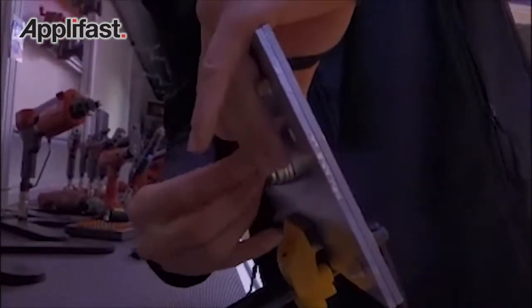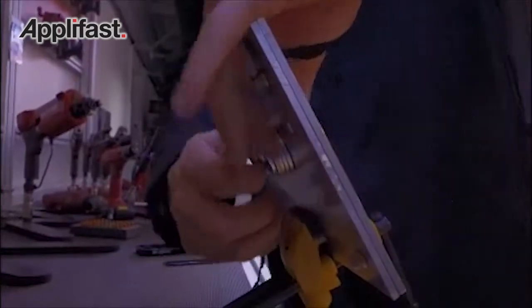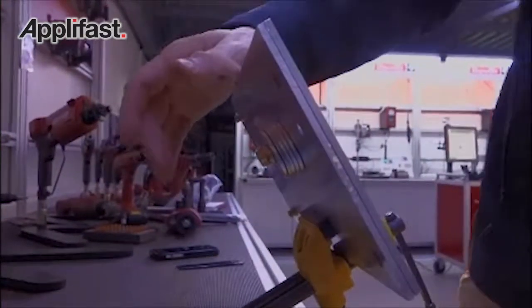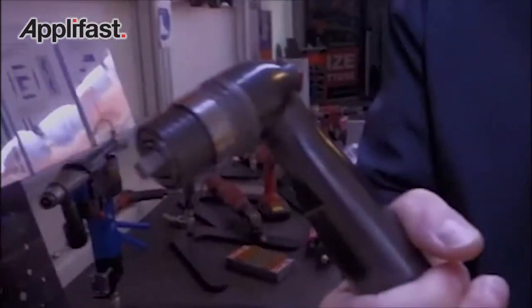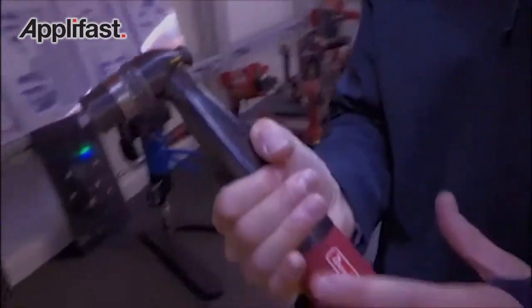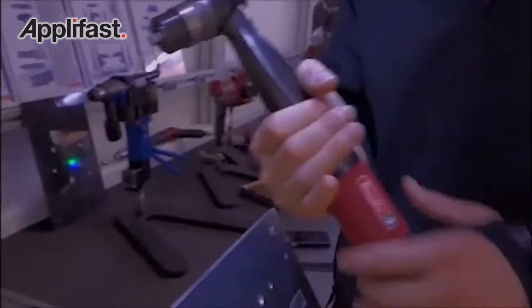In the tightening operation, I will use an EAB com with quick release head. Same principle, we've got one tool and several heads, depending on the applications. So my system will automatically send me to the right crowfoot. So I will pick up the crowfoot which is blinking, and then my tool.